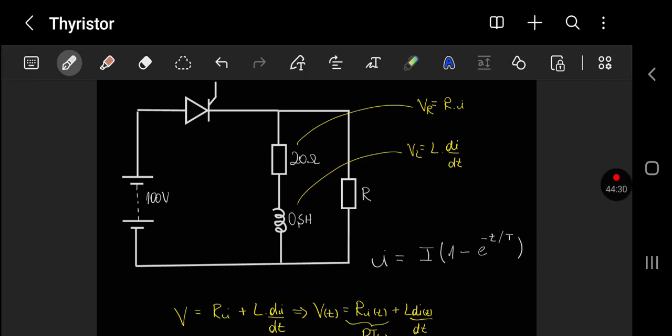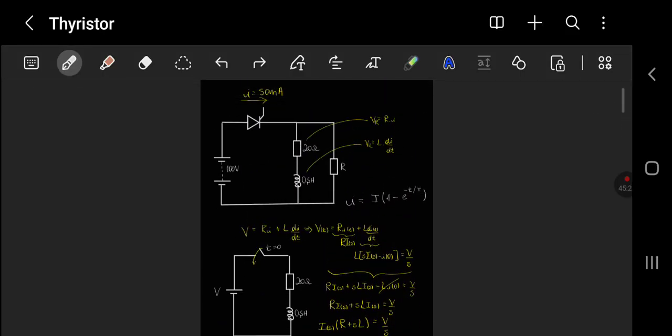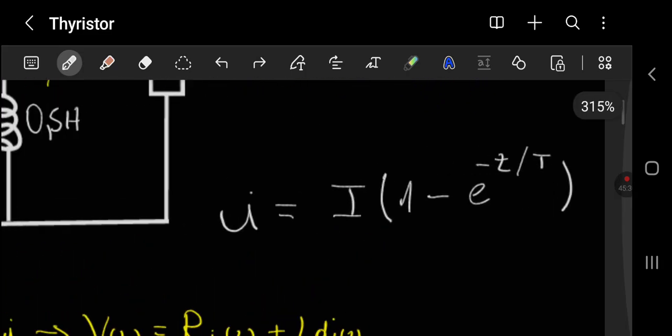So that is the end. And he says, observe that in this case, how 50 microseconds is less than the value of the time constant T, which is 0.025 seconds, or 25 milliseconds, and the initial value of the di/dt is equal to 100 over 0.5, it could be presumed that this is constant after 50 microseconds, giving the current that we find, which is 10 milliamps.